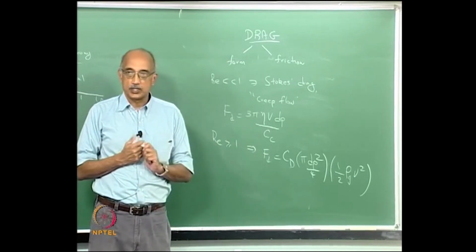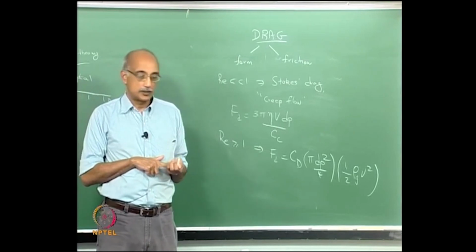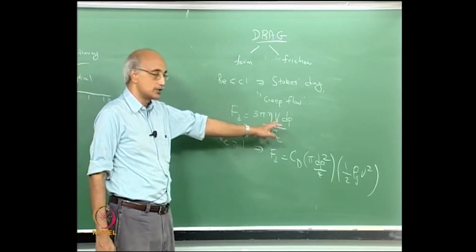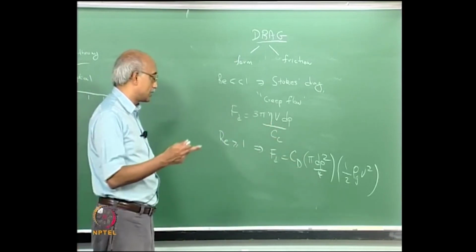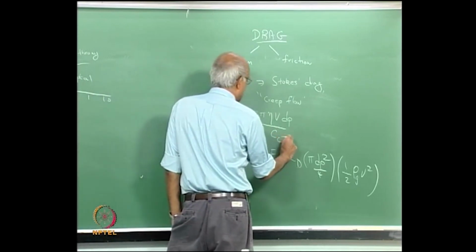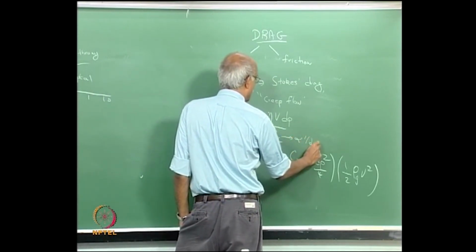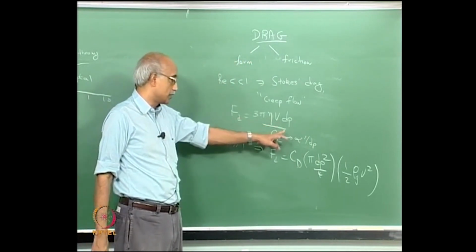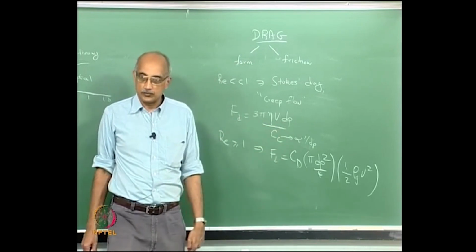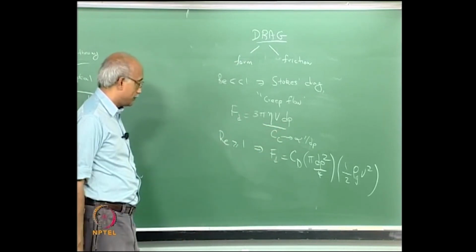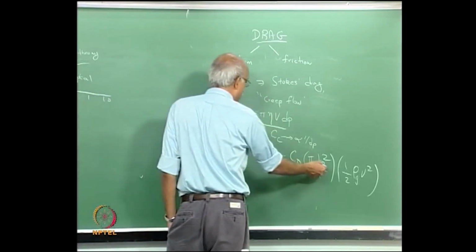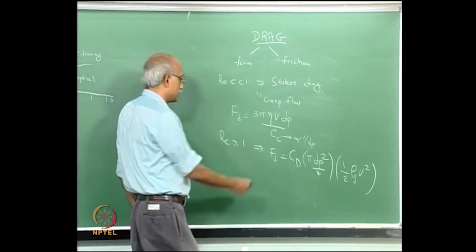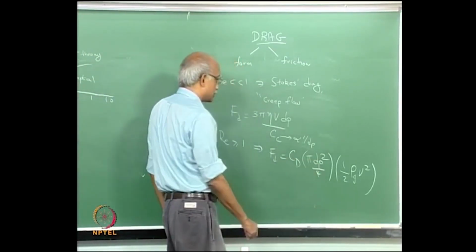And of course, the Stokes-Cunningham correction factor being in the denominator is something you have to be careful about. It may look apparently like the drag force is proportional to dP, but remember that as particles become smaller, Cc is actually proportional to 1 over dP. So the actual dependence of drag force on particle size is dP squared for very fine particles. It is not equal to dP. Same as for the case of larger Reynolds number drag, where the drag force is proportional to dP squared.